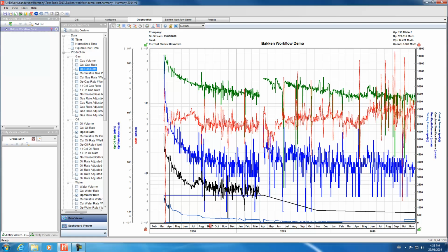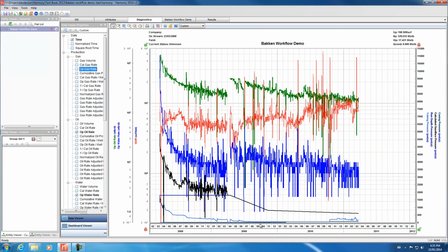And the well flows up until approximately April of 2009, and then it goes into pumping. So the well is now on artificial lift from this point going forward. As you can see, the calculated bottom hole pressures are shown here in black. These are calculated from a multi-phase pressure loss correlation, and then from the point where it's artificial lift going forward, we really have limited data on what the bottom hole flowing pressure is.